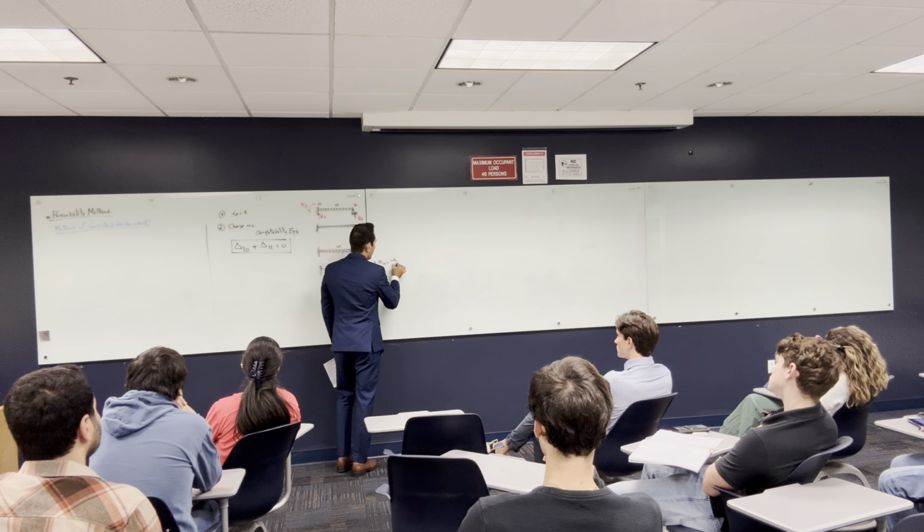And this one is called RA1. All right? But this one is like a unit load. So let's call it R small A1. Okay? That comes from the unit load. If you want to find the final reaction, you have to sum this reaction and sum this reaction, right? If you want to find RA, it is going to be equal to RAO plus RA1, right?